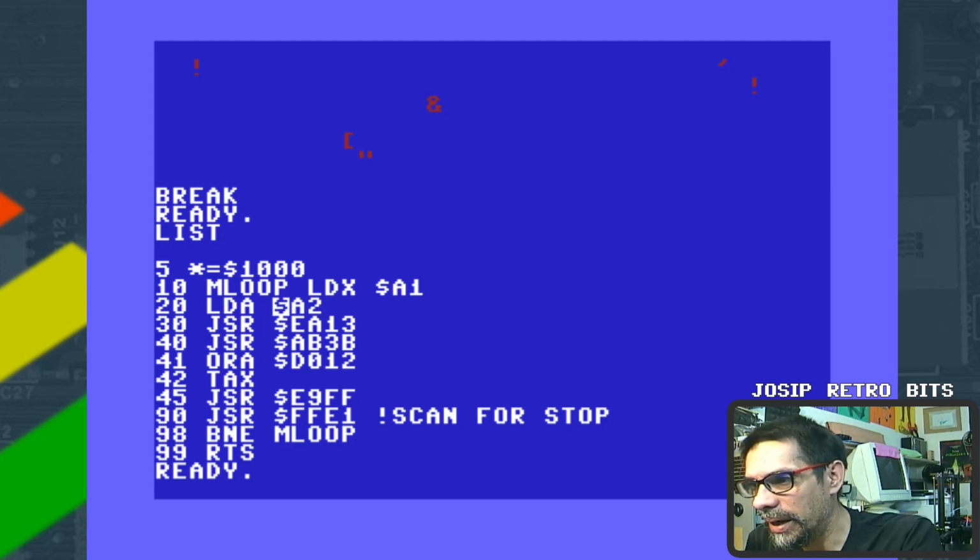The least significant byte is located at memory address A2, then the middle one is at A1, and the most significant byte is located at A0. Now you can imagine that this A2 value is iterating or looping from 0 to 255 quite fast.